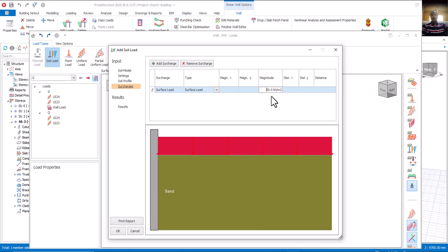So that's why we are going to be using the vehicular load. And since it's a compound, sorry, a church, there are vehicle activities. For the small vehicles, we have 10, while for the big vehicles we have 20. That's the HB load. HB load is 20, HA load is 10. Understand? Though there are situations whereby it might be more than even 20, depending on your consideration. Is that okay?